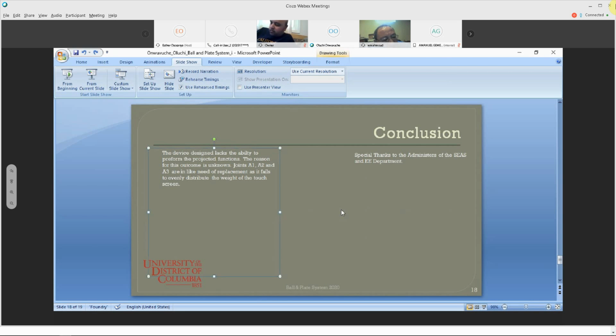So in all those cases, you have the X and Y, which are touchscreen. But in my case, I had 3 servo motors, and so you cannot simply designate one servo motor to an X and then another one to a Y. What about the third one? In the video clips that we're seeing, they were designating the measurements from the touchscreen that is X to one servo motor, and the measurements from the Y to another servo motor.